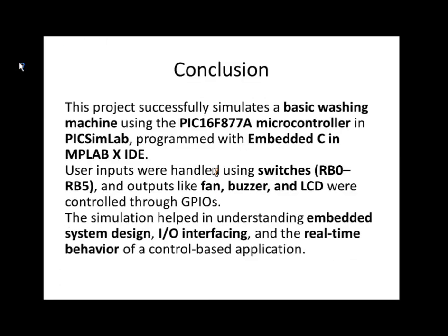So my PPT has come to the conclusion. This project successfully simulates a basic washing machine using the PIC16F877 microcontroller in the PICSimLab program with MPLAB X IDE. User inputs were handled using switches RB0 to RB5, and outputs like fan, buzzer, and LCD were controlled through GPIOs. The simulation helped in understanding embedded system design, input-output interfacing, and the real-time behavior of a control-based application.